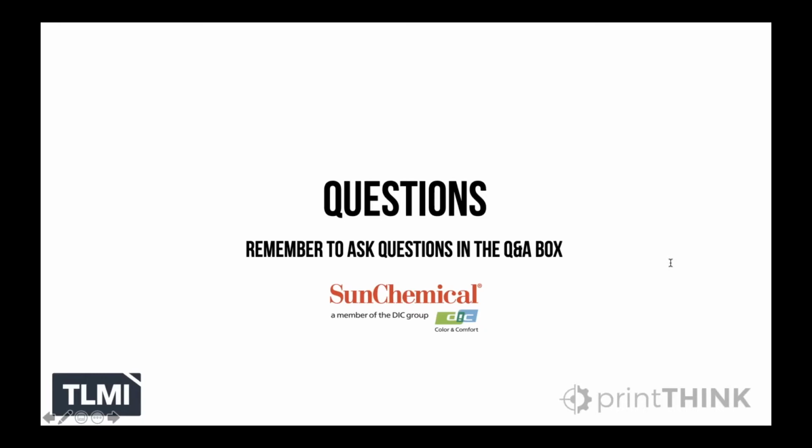Okay. We have another question. Can you expand on the topic of low migration? What exactly is that? Dave, do you want to take that? Yes, I'll take that. In terms of low migration, we're looking at materials of construction in the ink which will not migrate, and also the cross-link matrix that the UV ink is made of will be tight, and there will be no chance for things to migrate through or diffuse through in the ink.